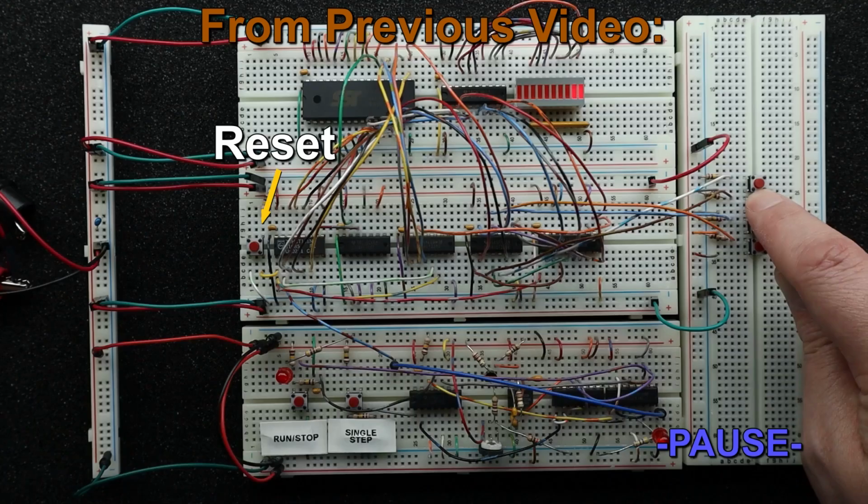As I held down the reset switch, that provided enough time for the first instruction at address 0 to appear on the outputs of the flash memory chip. This means that the operand value of 3 was provided to the adder from the flash memory chip. And since I wasn't pressing any of the value input switches yet, the adder was adding 3 to 0 and providing a 3 on its outputs. Also, since the reset switch is pressed, the decoder was disabled, providing a low on all of its outputs.